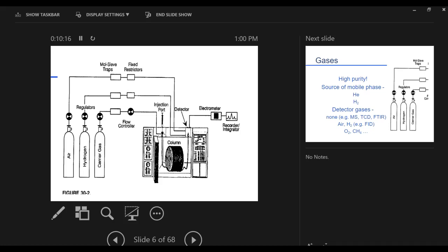So anyway, the slide we were looking at, basically, it shows a flame. And so as our analytes come out of that column, the analytes go into the flame, and they get burned in that flame. And across that flame, we put electrical potential. So we've got a ground here at the bottom of the flame, an electrical ground, and right above that flame, we have another potential of about 300 volts. And when things are being burned, there's ions in here, we basically carry electricity across that flame. If there's no analytes being burned, we can't carry any electricity.